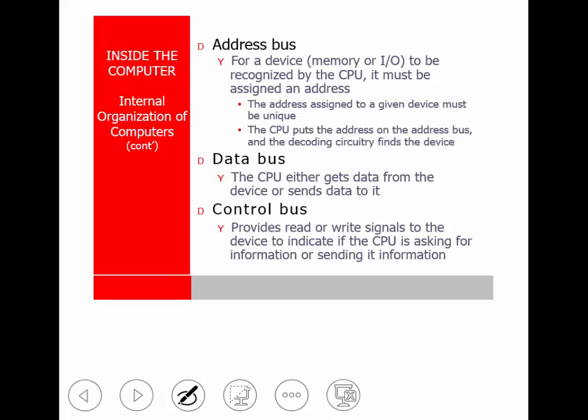The data bus is bidirectional, and it's very tricky when you deal with the data bus because every memory chip, every I/O chip, and the processor all can write to the data bus. Obviously, they can't all write to the data bus at the same time, because then you end up with smoke coming out of your computer system, or out of your microwave oven where the digital control board is, or out of your phone. Bad things happen when 2 devices write to the same bus at the same time. So that's really where the control is.